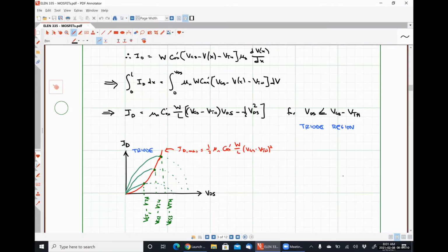All right, when we left off last Friday, we were talking about NMOS transistors, specifically operating in the triode region. So today, let's continue that discussion by looking at what happens when VDS is very small in comparison to the quantity VGS minus VTH.